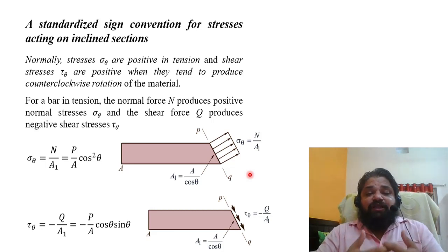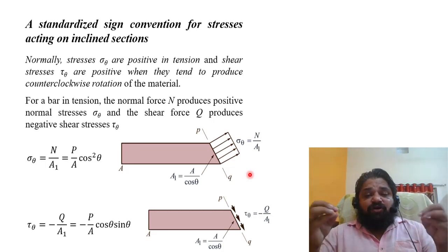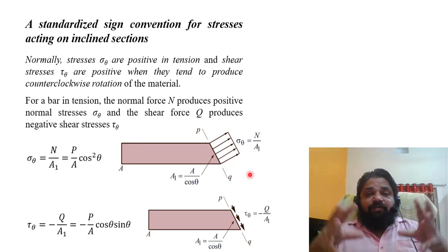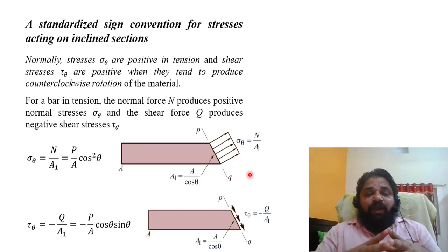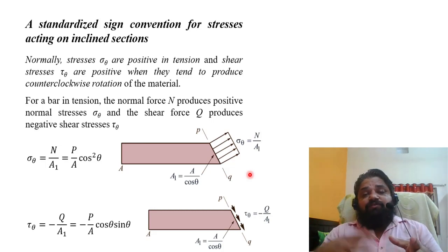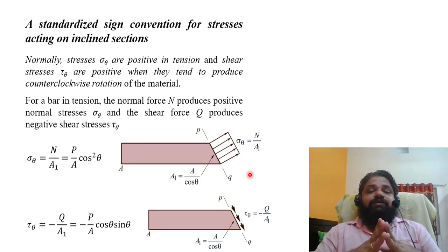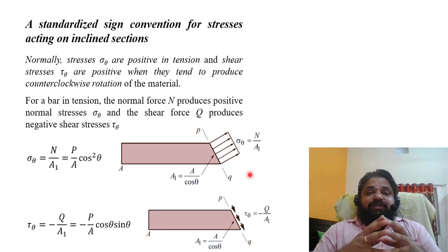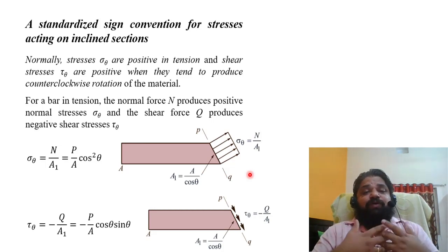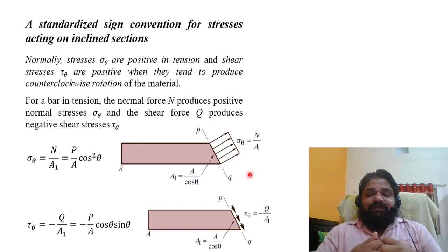Most probably we are talking about the resultant stresses, because the stresses are coming on a structure or on a point, on an element, in a gathered manner or in a group, and from that group we are calculating the stresses, again in the form of normal and shear individually. Now, sometimes I can also define the principal stresses in this form: the stresses which are developing on a principal plane are called the principal stresses.